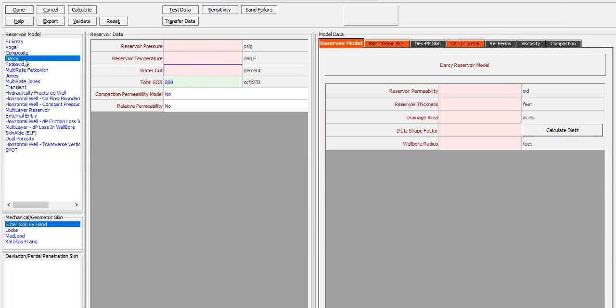In this video, I will show you how to create the IPR data model using the Darcy equation, with relative permeability. So it will be more interesting, and also to show the well test data, to plot the IPR with the well test data also, and the sand control. All right, so it will be very interesting and comprehensive.